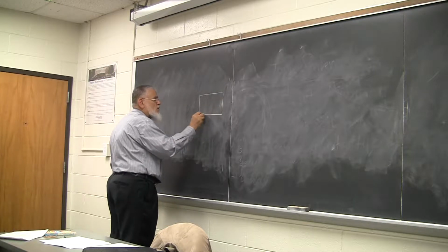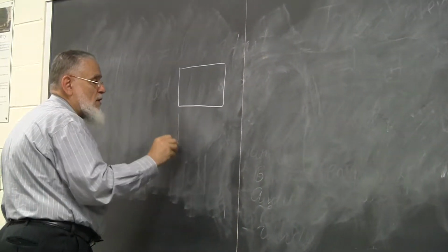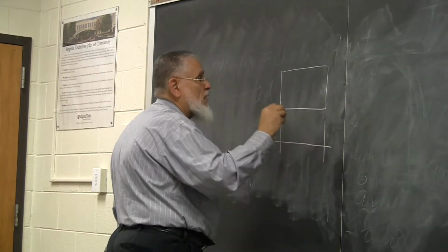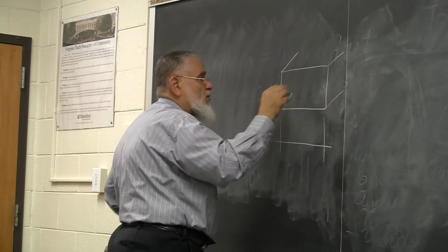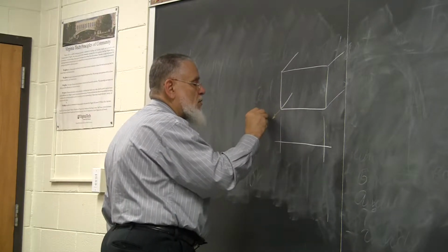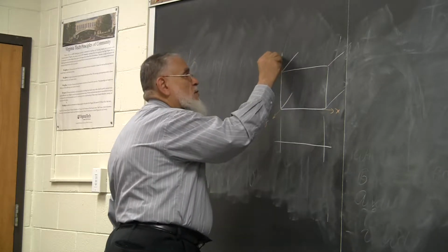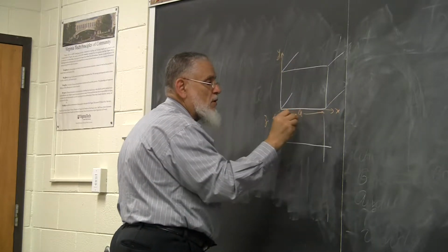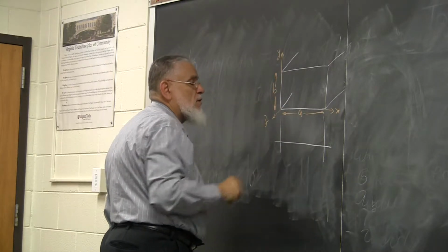We look at the cross-section here. We discovered that the field pattern must be 0 at the edges here. Tangential field, that is, because we're talking about E sub z, and E sub z is tangential to the conductor. This is the z coordinate, this is our x, that's our y, and we chose the broad dimension on the x-axis and the narrow dimension on the y-axis.